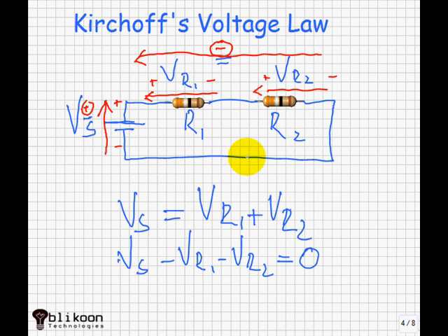If we take Vr1 and Vr2 across the equal sign, we get something like this. And this is the general form of KVL. Notice that we've got these minus signs in front of the Vrs. These stand for the fact that they are energy consumers, and it's what I meant by these signs that are put here in the circuit.